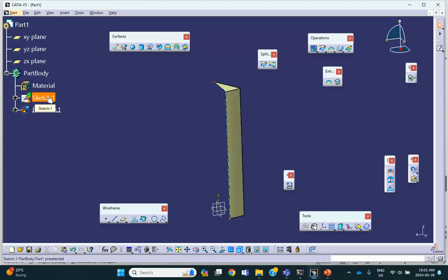No problem as far as applying restraints is concerned later on. But the other two edges are in none of these vertical planes, not YZ, not XZ, obviously not XY. So that's why I'm going to create a local coordinate system here and use it. Right now, I'm going to do that.